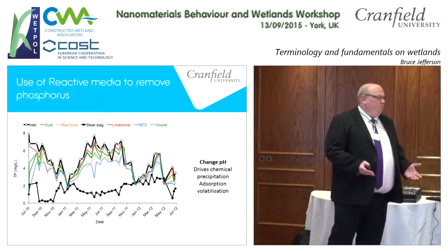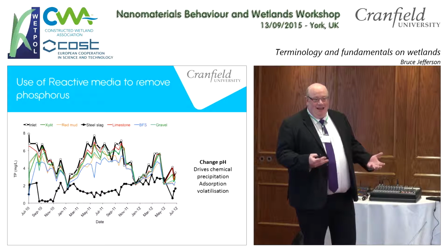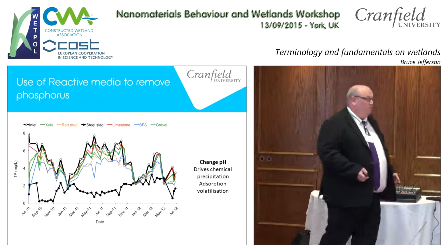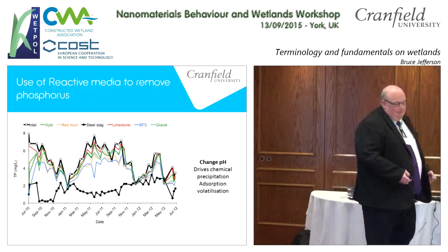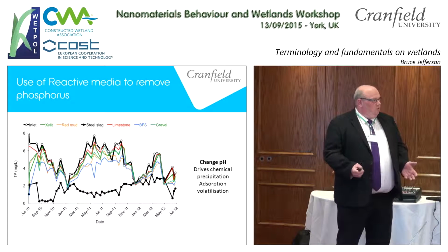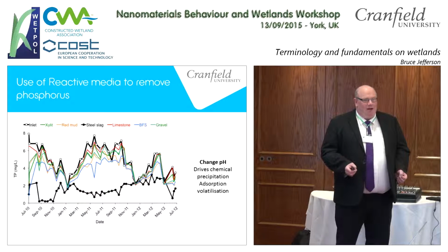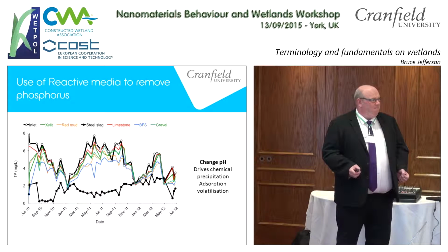The other one is phosphorus, and quite a lot of the talks at the conference are about how do we deal with phosphorus in wetlands. Probably the preferred solution at the moment is to use not gravel, but a different material that provides a reactive process. Generally that means calcium oxide dissolution.